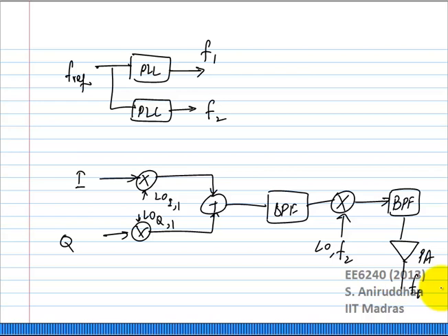The other way you could think of this, the PA has a certain power on transient. Now, how fast you turn on will also decide how strongly it pulls different frequencies. The rate at which you turn on the PA will also determine how strongly it pulls, and this will be a function of frequency. Okay, if you do a transmitter like this, it is a heterodyne transmitter.